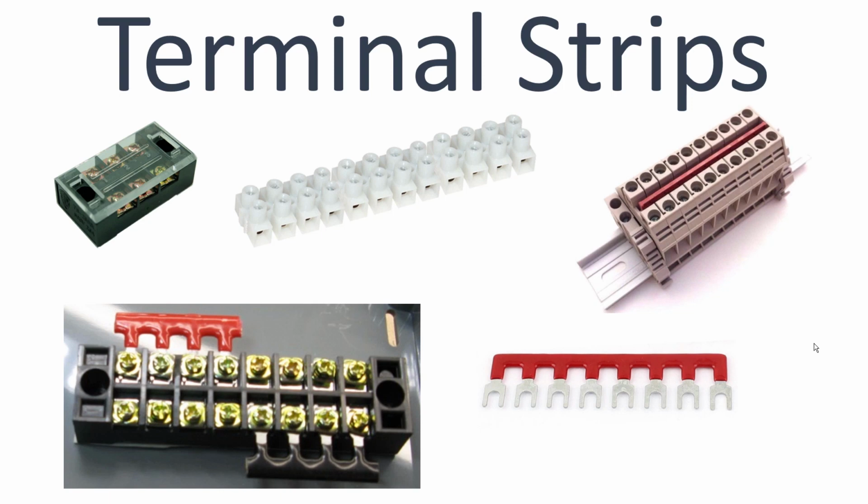You can put 2 ferrules underneath each screw pad. So that means in those 4 connectors or 4 screws, I can put 8 ferrules underneath those 4 screws. So this is a good idea. And by the way, you can buy these jumpers on eBay or Amazon. They're dirt cheap. Matter of fact, it doesn't even matter what color they are. The electrons don't know what color of insulation is on the jumpers.